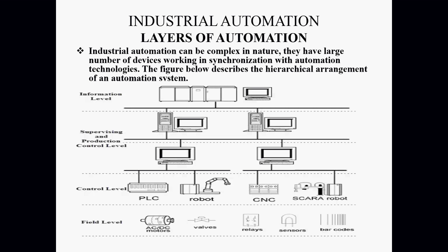Now the PLC can only follow the logic that I have written there. So although I wanted the valve to close, if by error I have written my logic so that the valve should open, the PLC will not be able to make a decision on this. If I have written the logic to open the valve, although I wanted it closed, then the PLC will open it, right? Yes, sir. So that is why the PLC does not have its own intelligence.